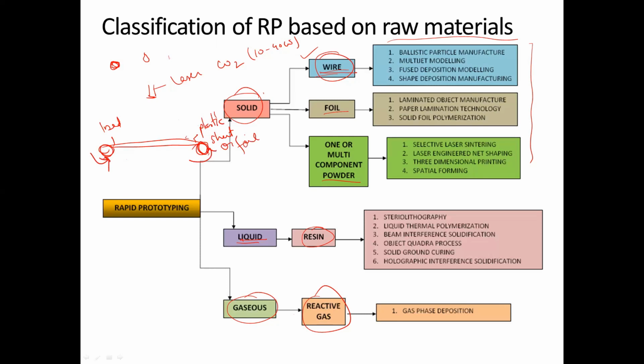Okay. So as this starts to wind, this sheet will start to move over here. On top of here, we have what we call a hot roller. What happens is, this plastic sheet is actually going to move in this direction. As it moves, it comes to a stop at a certain distance. That distance is defined by the bed which is underneath this plate.